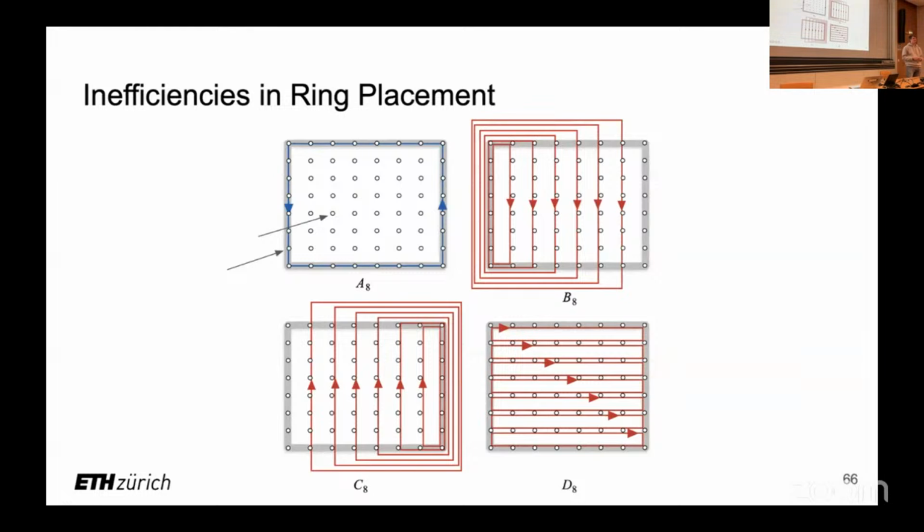Exactly. And this problem becomes increasingly worse when you go to bigger designs, right? Because say you had a 16 by 16 core design, your two cores are basically only 4 apart in Manhattan distance, yet you have to travel your entire chip's width to send one packet back and forth. And that's also obviously really inefficient.